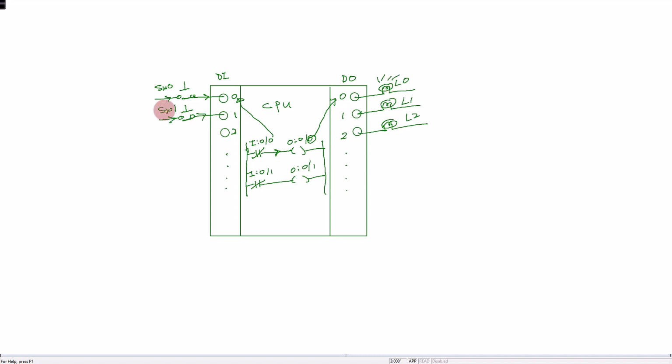Similarly, if switch 1 is pushed to close, the actual current can flow through the circuit to energize the digital input 1 internal LED 1. Because the LED 1 is energized, it will trigger its relevant virtual switch. In this case, it's normally closed to open. So it will trigger it to open. Thus, virtual power cannot flow through the circuit, and this virtual output coil will remain de-energized. So nothing will happen for this bit 1, which is linked to input terminal point 1.